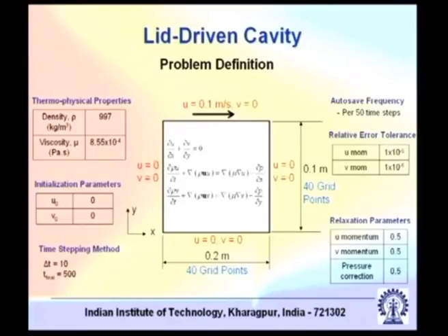Say you have a boundary layer flow. When you have a boundary layer flow, you require to capture the strong gradients of velocity and temperature or whatever, depending on what type of boundary layer it is, within the boundary layer. To do that you require to have a large number of grid points within the boundary layer, at least a substantial number of grid points. So if your gridding is such that you do not have any grid point within the boundary layer, say one is at the boundary and the next one is outside the boundary layer, then you are not able to capture the physics within the boundary layer.